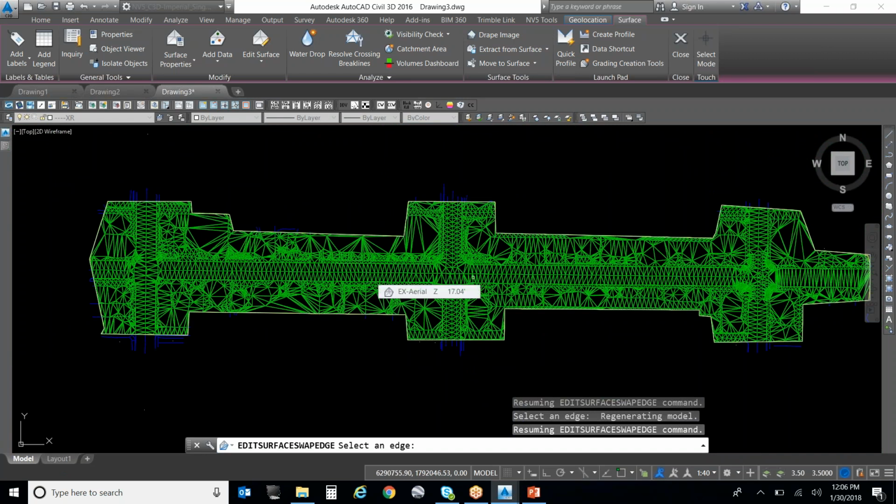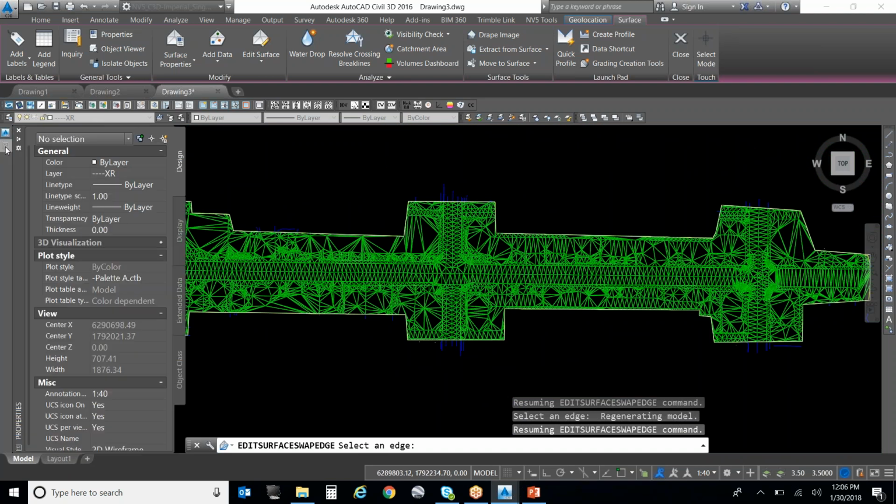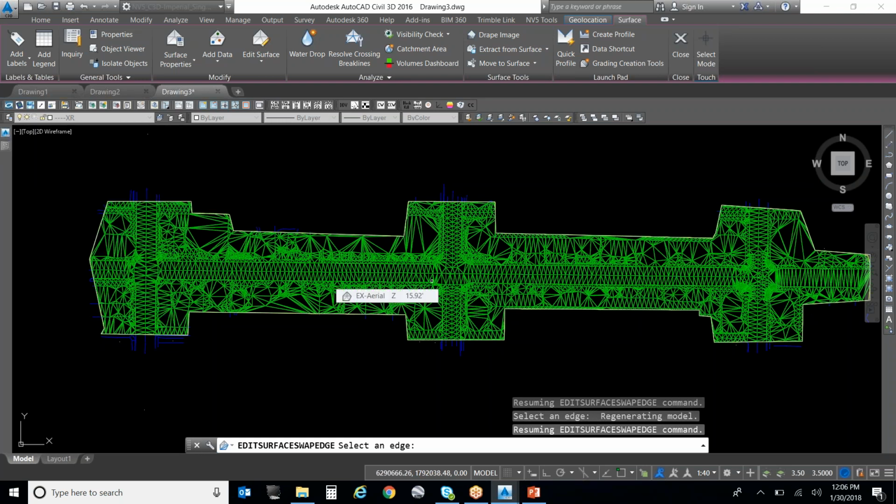So if I were to add survey information, how would I do this? You have points. Right? So if I had a bunch of survey information, okay, I'd add the points. How would I make the surface for those points? You would import them into the definition of the surface. Right, but if I do that, you're going to corrupt this surface. Create a composite surface. Okay, what I would prefer that you do is create a surface just from the survey points. You should have enough definition in your survey points to create the surface just from the survey points.